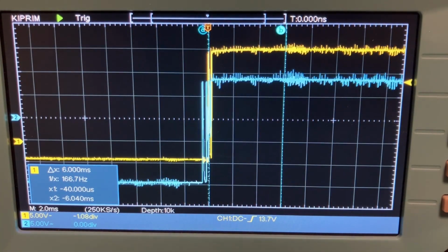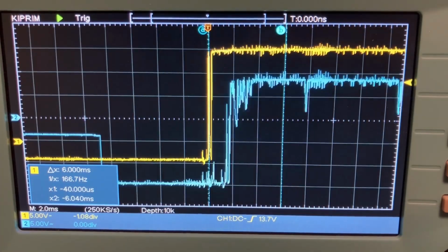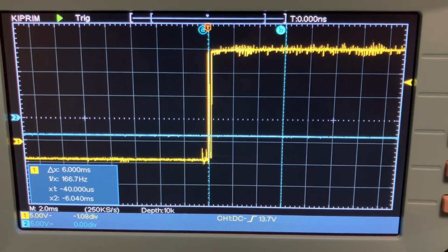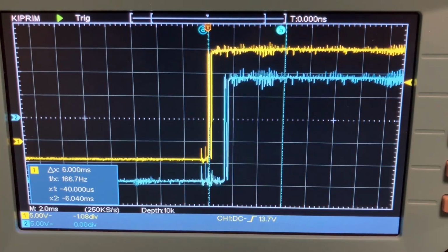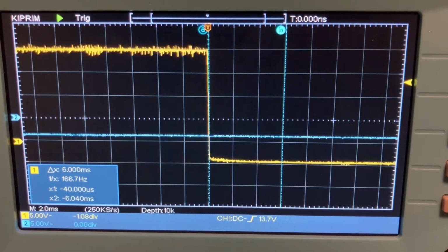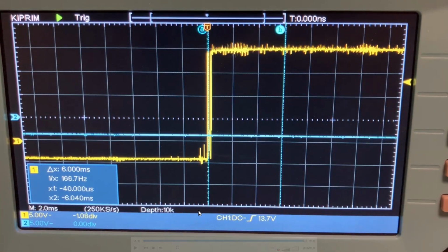This is a little bit faster. These are 2 milliseconds. That's relatively slow. Also not close to 2 milliseconds. As we can see here in these diagrams, at least 2 of the relays are completely defect. So it's no wonder that the relay system is not calculating the correct value.